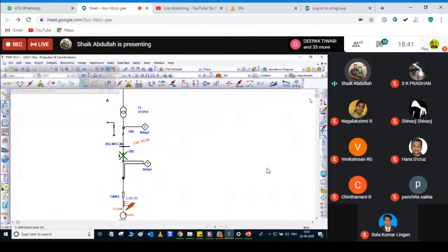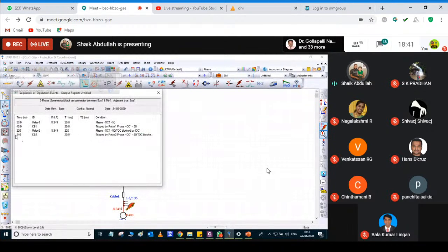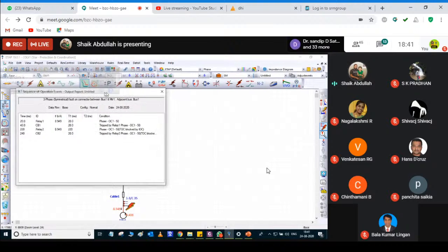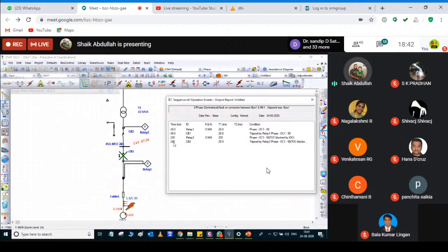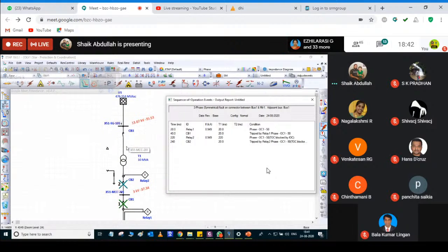You have to do proper relay coordination and achieve the lowest time of operation, the lowest fault clearing time. That is the important thing. Based on that, you are going to design your switchgear short time rating, breaker short time rating, and the arc flash requirements of each and every bus, this bus and this bus.